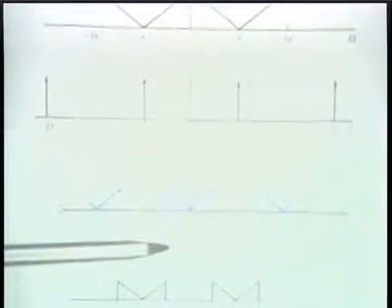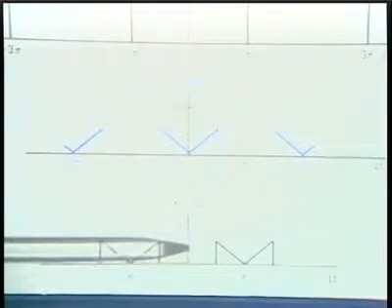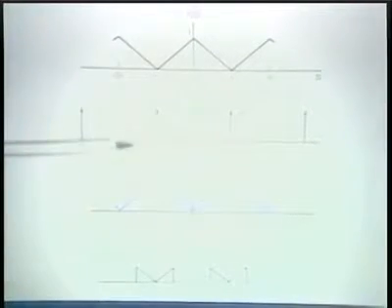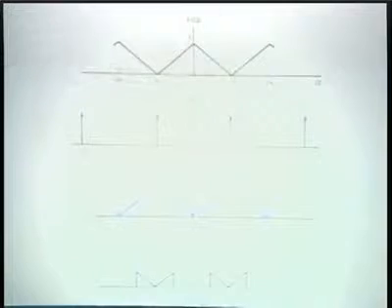Namely, it's shifted back to be centered around minus pi and around plus pi. So if we compare this spectrum with the original spectrum at the top, what we can see is that, in effect, we've extracted a portion of this spectrum equivalent to processing with a high-pass filter.